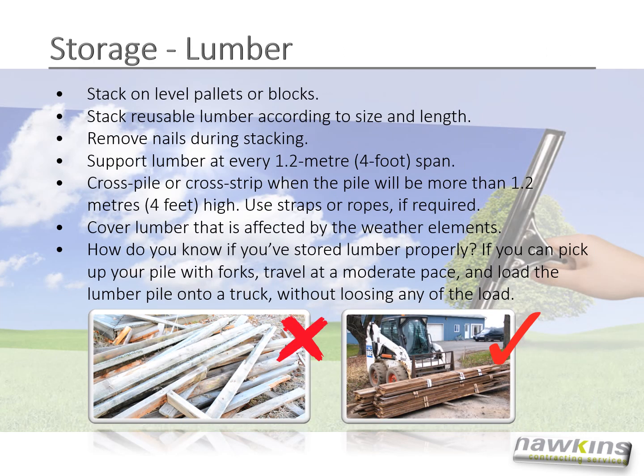When storing lumber, stack on level pallets or blocks. Stack reusable lumber according to size and length. Remove nails during stacking. Support lumber at every 1.2 meter span. Cross pile or cross strip when the pile will be more than 1.2 meters high, and use straps or ropes if required, and cover lumber that is affected by the weather elements.